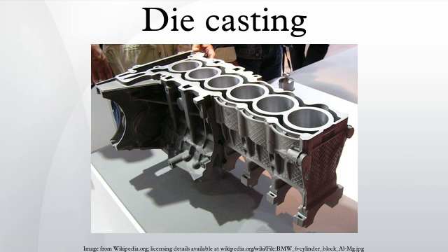Semi-solid. Semi-solid die casting uses metal that is heated between its liquidus and either solidus or eutectic temperature, so that it is in its mushy region. This allows for more complex parts and thinner walls.